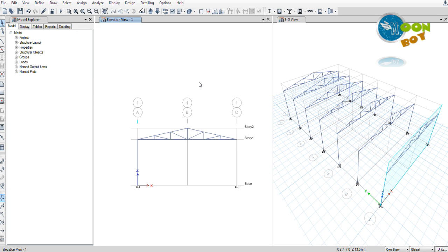Now on that we have to place the sheet roof, that is truss sheet roof, and we have to place the purlins joining below the sheet roof. So let us go for the purlins now. The purlins will be at 0.5 meters or 0.7 meters center to center. So the purlins are nothing but the supports for the sheet, which are below the sheet and on the rafter.